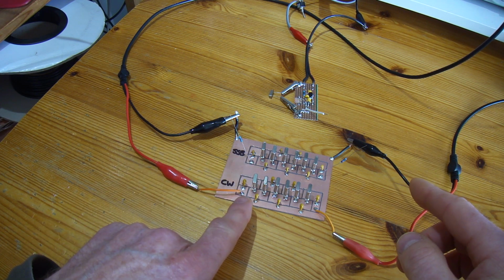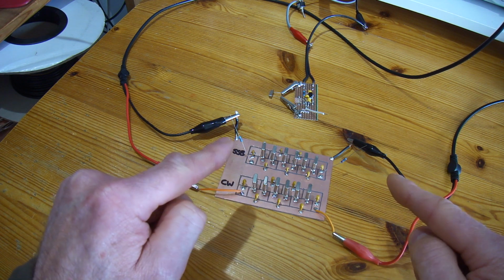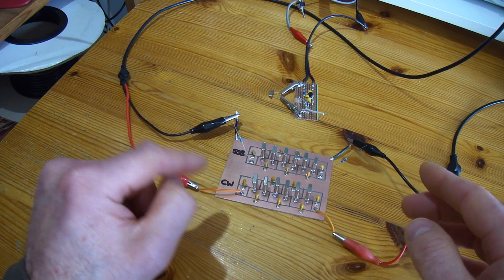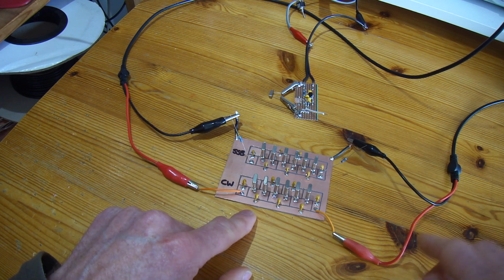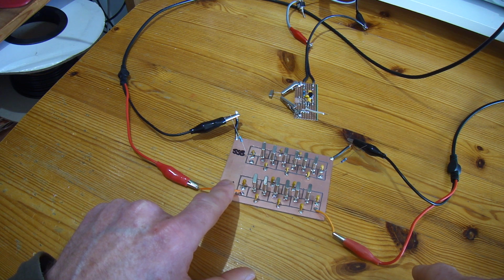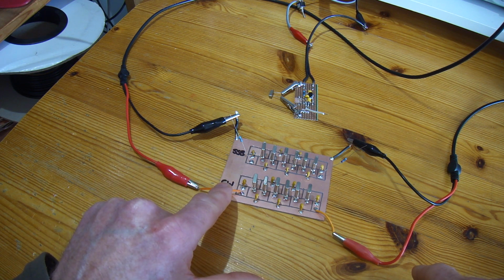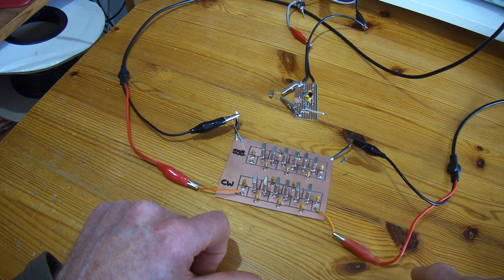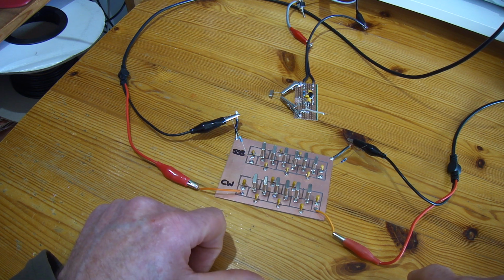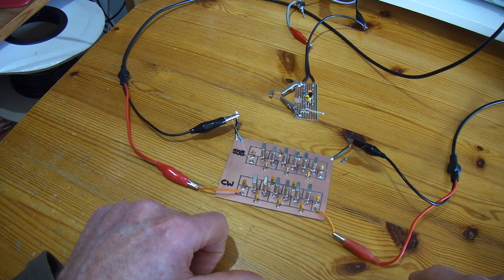And then for the CW, for this type of filter, the higher in capacitance you go, the narrower the bandwidth, and that got down to 330 picofarads. Insertion loss for the CW, slightly higher with the bandwidth, so minus 11, so not ideal, but hey, I'll give it a go. And the SSB was minus 6 dB. So I'll live with that.